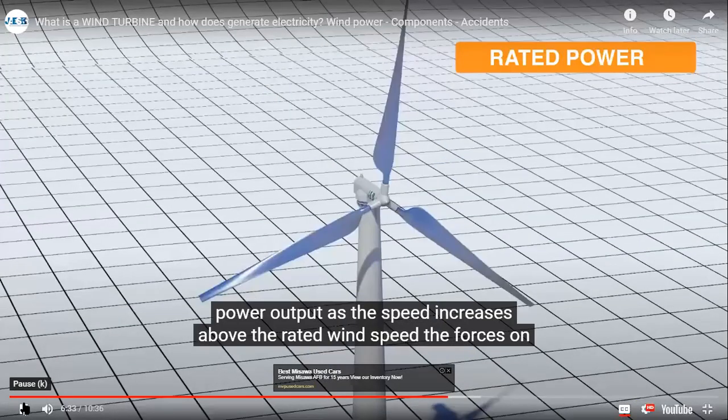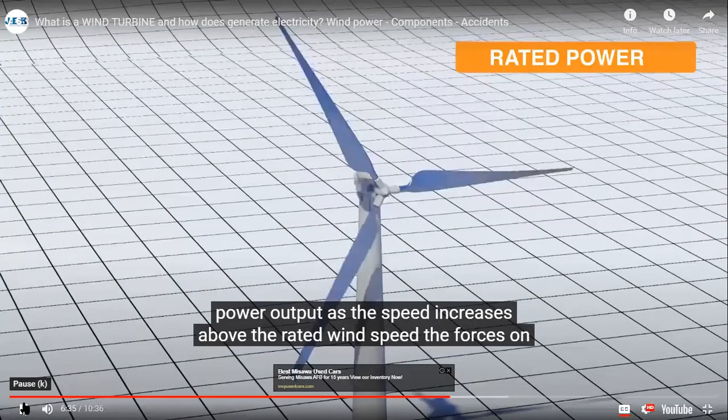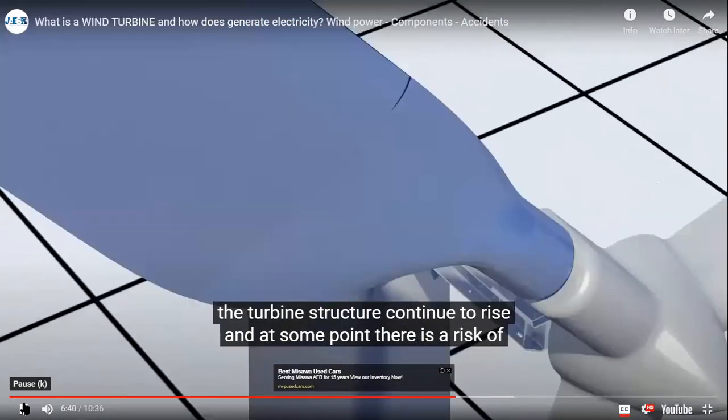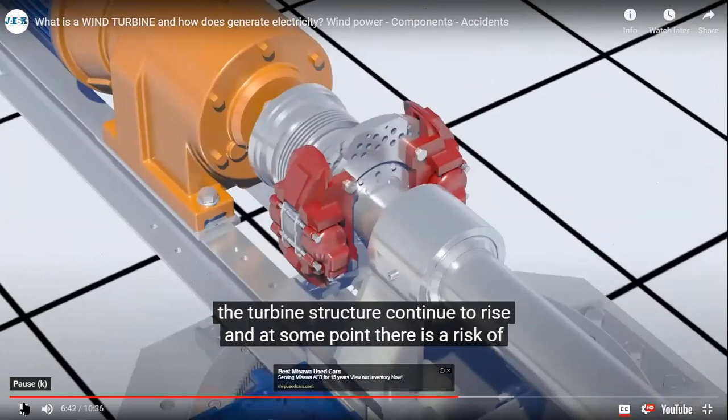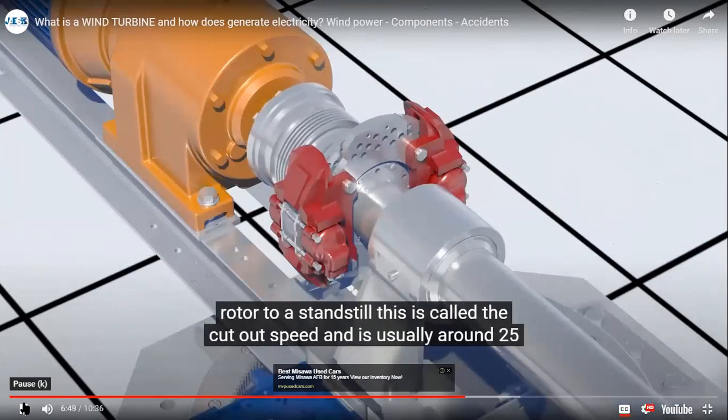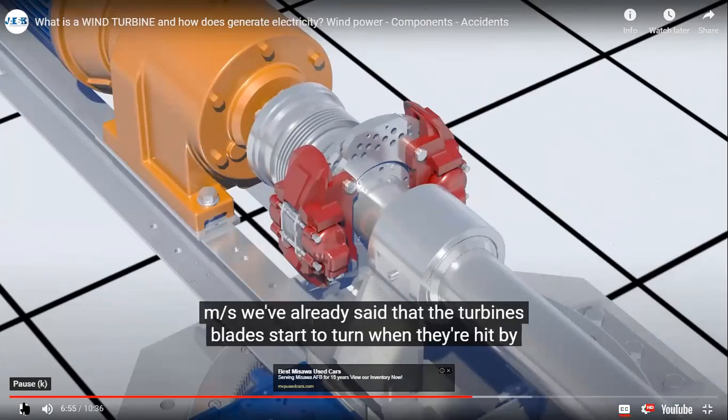As the speed increases above the rated wind speed, the forces on the turbine structure continue to rise and, at some point, there is a risk of damage to the rotor. As a result, the braking system is employed to bring the rotor to a standstill. This is called the cut-out speed and is usually around 25 meters per second.